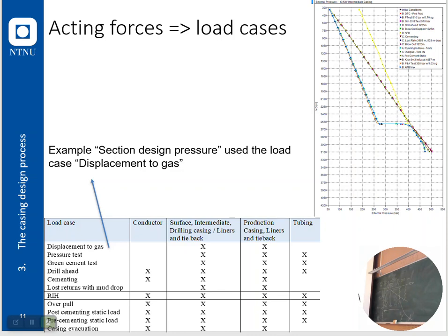The only difference would be that you have basically a different liquid situation in the annulus. That's it. If you wait until the cement sets up and you do the regular pressure test, then it's hard cement on the outside.